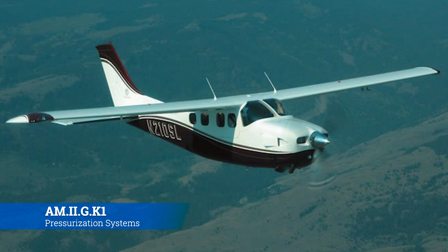The same kind of rules apply. That fuselage is made to take a certain amount of pressure, and anytime you're installing different STCs or whatever on that aircraft, you have to be very conscious of what that could potentially do to the pressurization features of the aircraft, because it's going to have a differential pressure limit just like a 737. It's probably not nearly as much, but you could effectively pressurize this thing like it's on the ground, put the cabin altitude at zero, and then take it all the way up to 26,000 feet or whatever its service ceiling is, and it could potentially have an explosive decompression event. So be really careful about working on the exteriors of these aircraft.